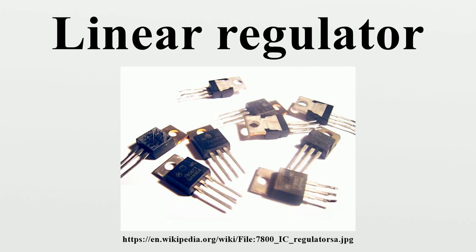By contrast, a switching regulator uses an active device that switches on and off to maintain an average value of output. Because the regulated voltage of a linear regulator must always be lower than input voltage, efficiency is limited and the input voltage must be high enough to always allow the active device to drop some voltage. Linear regulators may place the regulating device in parallel with the load or may place the regulating device between the source and the regulated load.